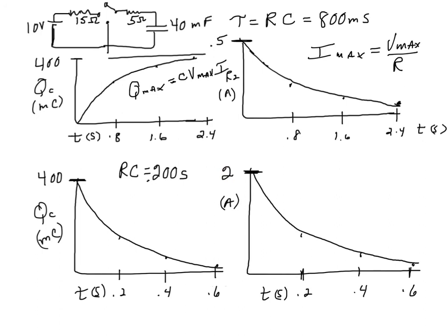And so the current will decay from 2 amps down to 0 amps, dropping about 2/3 of what's remaining each time, and about 95% discharged by the 3rd time constant, noting that the time constant is 0.2 seconds. And so that's the shape, and those are the numbers. Done.